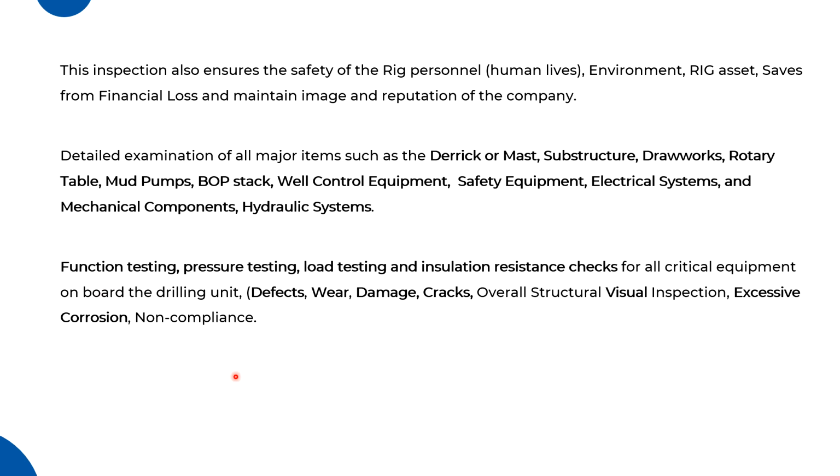Now, how are those equipment actually inspected? So equipment is inspected by function testing, pressure testing, and load testing, and insulation resistance check for all the electrical equipment on board the drilling unit.